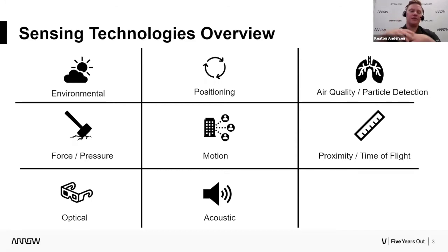And again, a lot of these sensors are going to have things like polling, where you're waiting for a keyword or you're waiting for a trigger before you then take a next step. So the power that you're having to use is keeping the sensor on at very small intervals so that you're not having to have it constantly on. It's just looking, wakes up, sees if the keyword has been present, and then if not, it goes back to sleep. So that's one of the ways that you can monitor battery control as well.